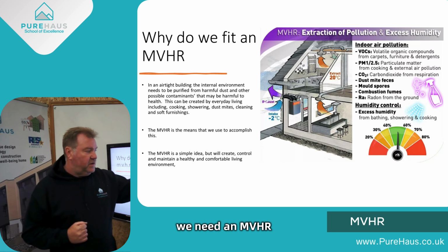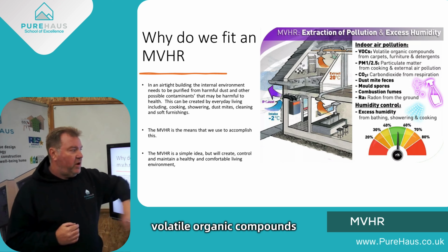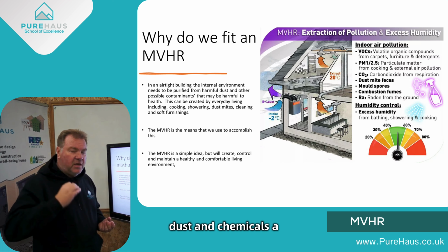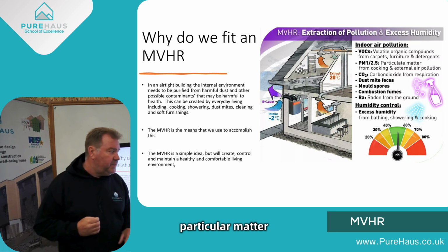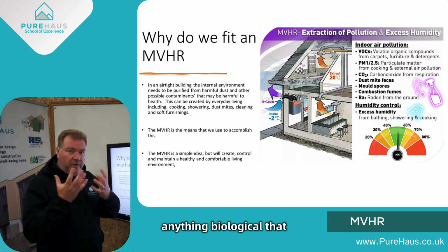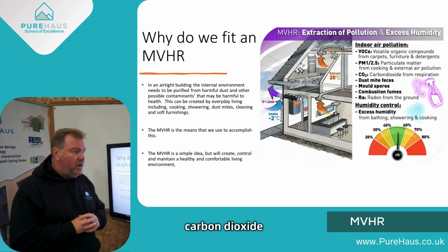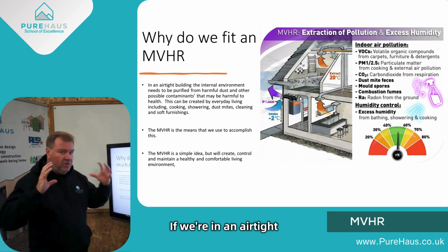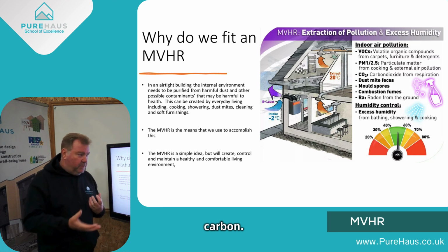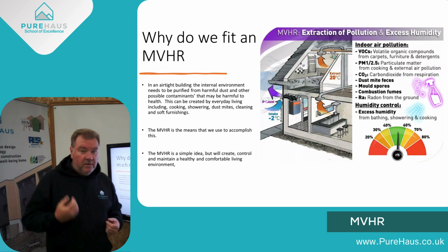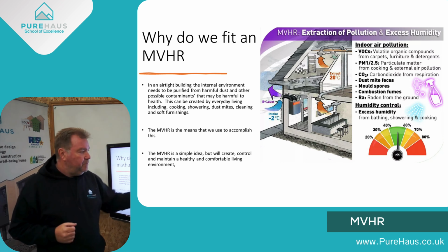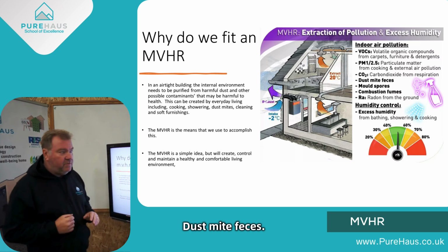We need an MVHR to take care of volatile organic compounds. This is your carpets and soft furnishings, which are producing dust and chemicals. Particulate matter from cooking and anything biological that we're doing inside. Carbon dioxide from respiration. If we're in an airtight box and we're breathing in oxygen and breathing out carbon dioxide, it needs to be dealt with. Respiration also puts damp into the atmosphere as we breathe. Dust mites. Dust mite feces.